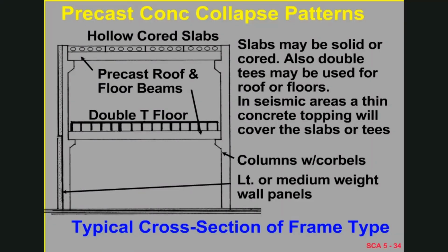Lastly, for earthquake collapse patterns, we have precast construction. The elements themselves are extremely strong. They're built in a factory, brought to a site, and connected together. And therein, as far as earthquake is concerned, lies the problem. If they're not connected together with very ductile and competent interconnections, including sometimes pouring a slab on top to connect everything together, they will tend to come apart.